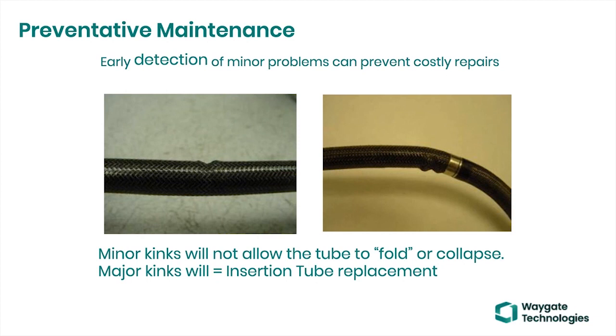So if you ever put one of these cameras in some Skydrol, you're going to see it melt in front of your eyes over a matter of a few minutes. The epoxy will deteriorate, the rubber Viton will swell, and you've just bought yourself some grief because it is going to come back to us for a rebuild. And that's the good news. We can repair those and rebuild them, but Skydrol and other cleaners like that are really detrimental to this.